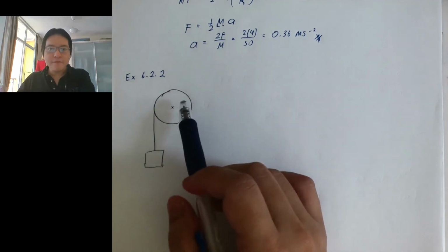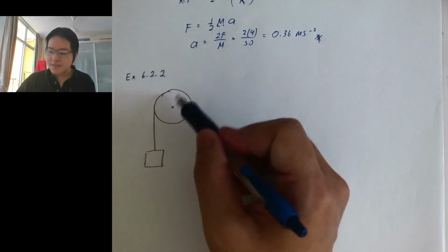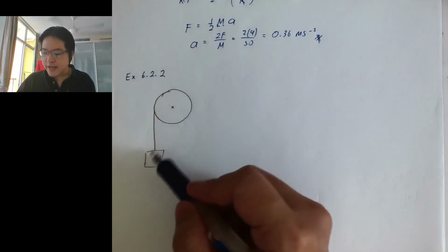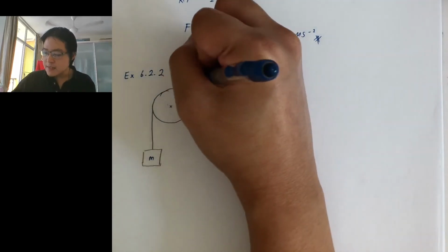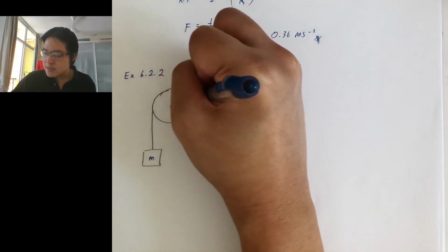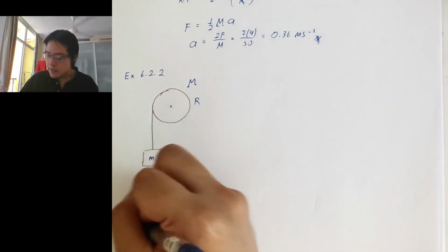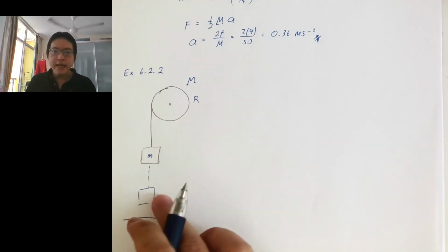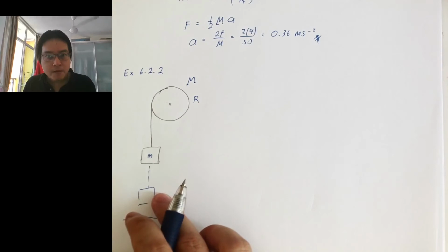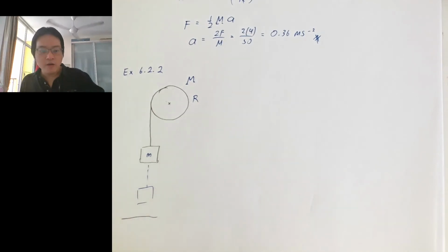So what we have here is a cylinder rotating with negligible friction, stationary horizontal axis. So it's just describing this picture. The free end of the cable is attached to a block. This block is having mass little m. This cylinder is having mass big M. The radius of the cylinder is capital R. So as the block falls, it will unwind and continue coming down over here, right? So it will be experiencing some acceleration. And from here, we want to calculate the acceleration of the falling block and the tension of the cable.